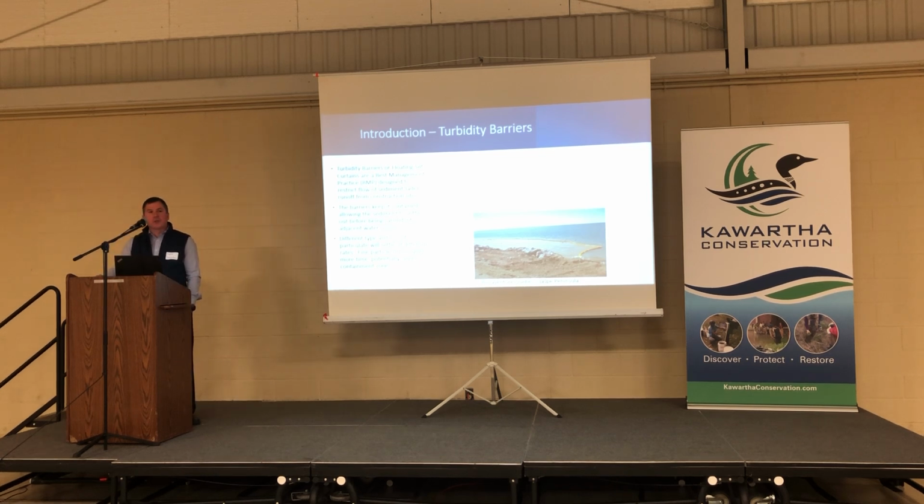And that's really the goal of these barriers, to provide a containment area and sufficient time that the sediment will settle out. Different types of sediment, different particle sizes will settle at different rates. For example, coarse clay will take up to 24 hours to settle inside of the containment area, in comparison to, say, a medium sand, which almost settles right away.